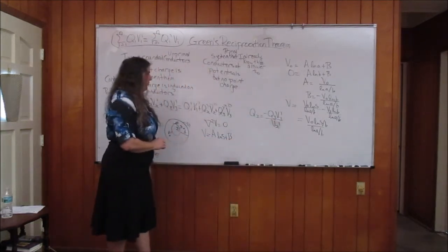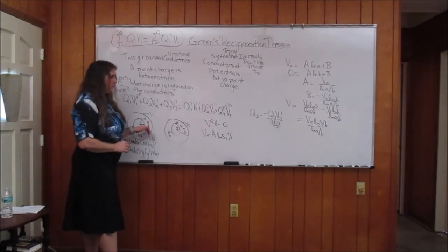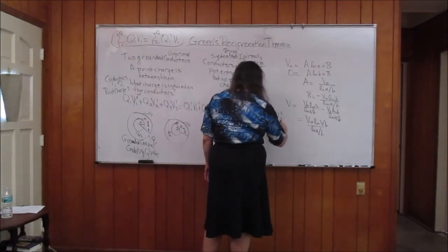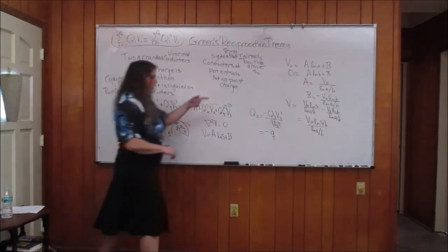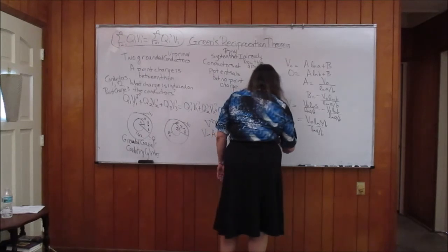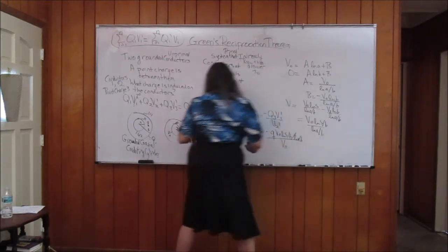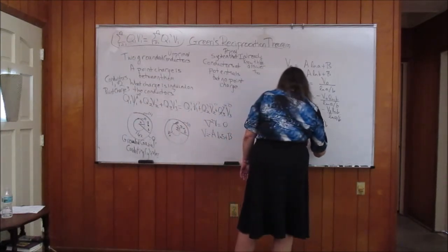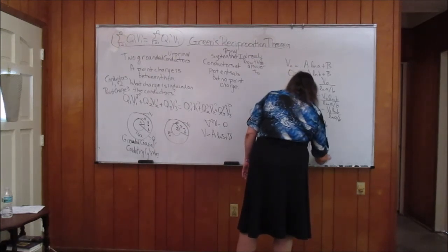Now remember, the 3 corresponds to the position of the point charge Q, and in our original system, that's equal to just lowercase q. V3 prime, that's the potential at that point. That's just going to be equal to V naught natural log of S over B over natural log of A over B, all divided by V2 prime, which is the potential on the inside cylinder. So this is equal to minus Q natural log of S over B over natural log of A over B.